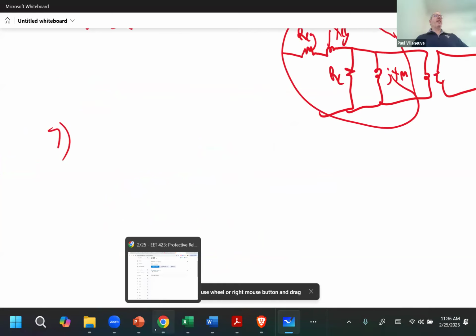If you remember the exam review, I actually talked about this. We have a current transformer, which has one turn of winding on one side, and then however many turns you need on the other side. It takes 1200 on this side and converts it to 5 amps on this side. The voltage drop across the load was 50 volts, right?